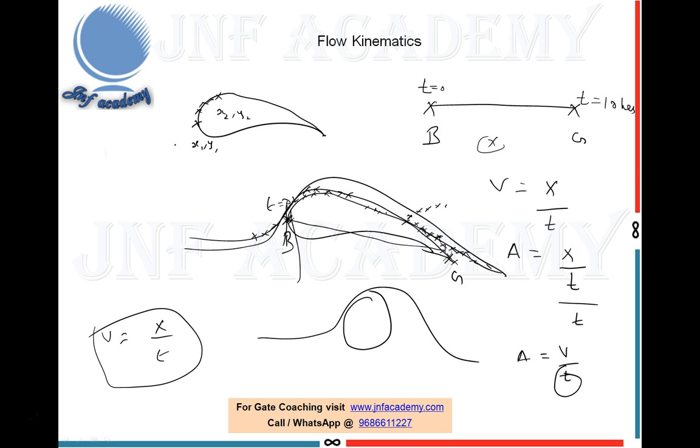So how are we going to convert this into a mathematical form? How are we going to approach this so that whenever a fluid particle flows through an object, you know that at this location this is the velocity, and at that location that is the velocity? You need to get an expression. You need to convert this physics into a mathematical model so that we can design our products. So let's start with that. The basic properties of the fluid particle are velocity and pressure. If you know the velocity change, then obviously the pressure can be calculated using Bernoulli's equation and so on. So how is the velocity varying at every location?